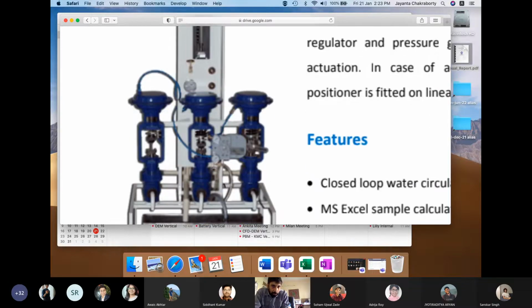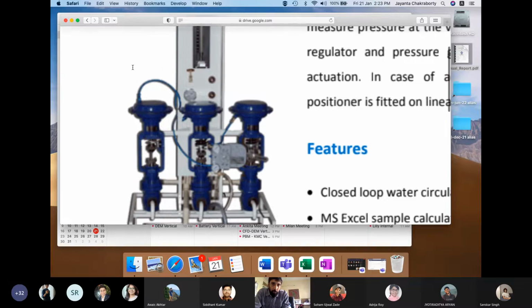These are the gauges which will read the valve top pressure. I'm not sure now. I'll go and see the setup, but I'm sure one of those reads it, but exactly which one I am not sure at this point. You can also read that valve top pressure ranging from 3 to 15 psi.